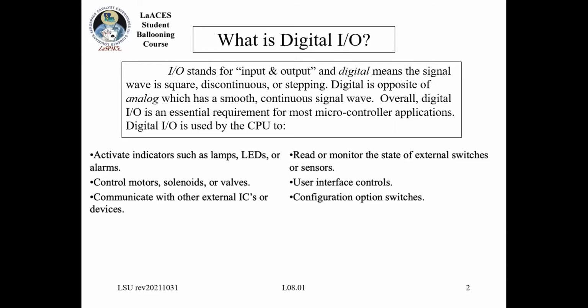So you can use digital I/O for all kinds of controls and interfaces. Anything that's just a simple on-off indicator, like an LED, a lamp, an audible alarm, right? Those are all very easy to control digitally. You can also easily read the state of anything that is a simple on and off itself. Like, hey, is this switch in an on position, right? That's the simplest sort of thing to do because it's only got one state.